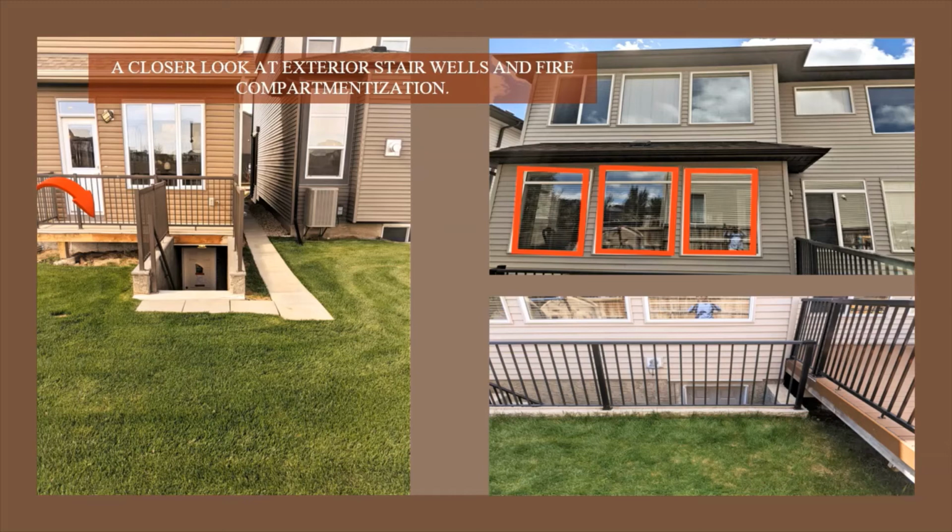And now I'll get into exterior stairs for a basement suite. You have to understand that upstairs is one fire compartment and the secondary suite is another fire compartment. To separate both fire compartments, we have to put some form of structure in between. This is in case there's a fire on the upper floor and the fire goes through those windows, we still need to provide a safe means of passage for someone to exit the suite.